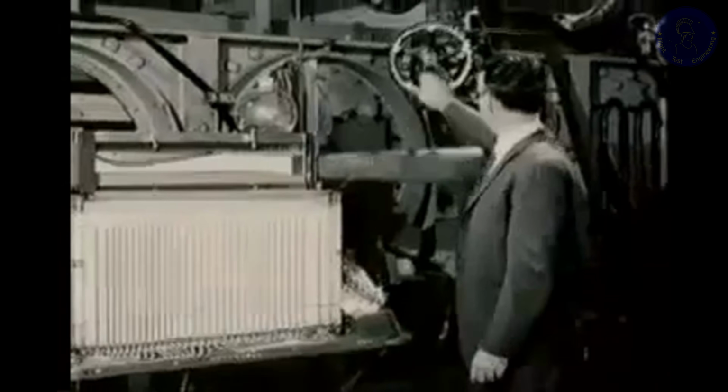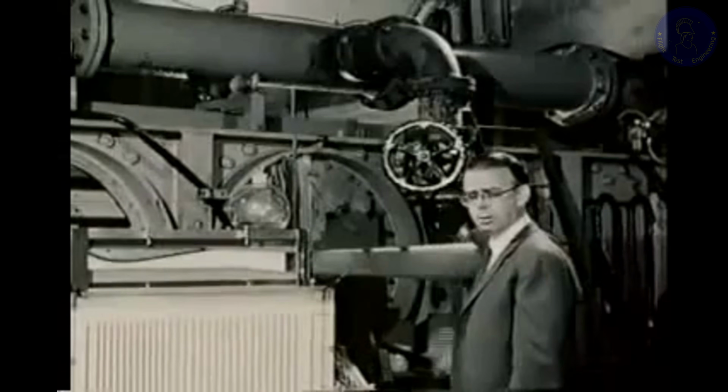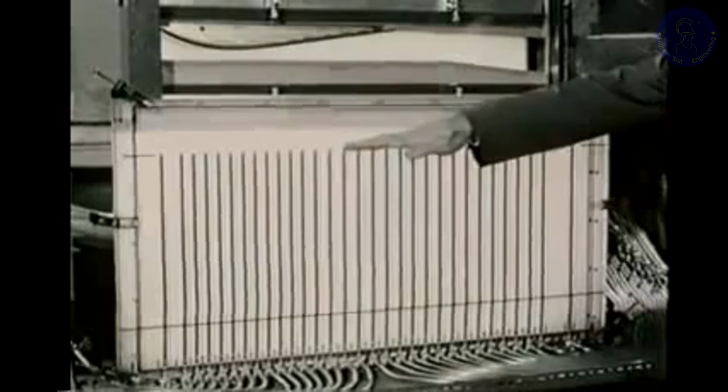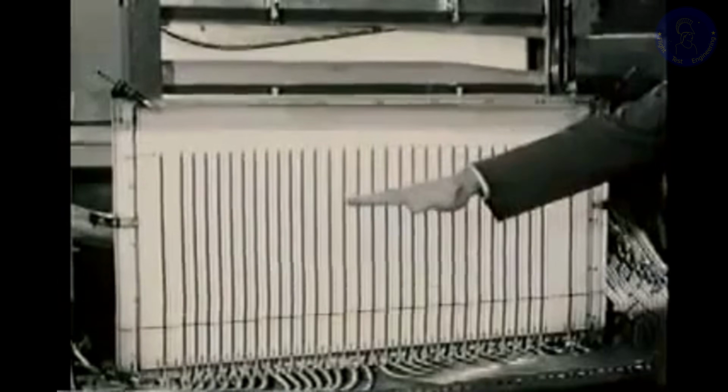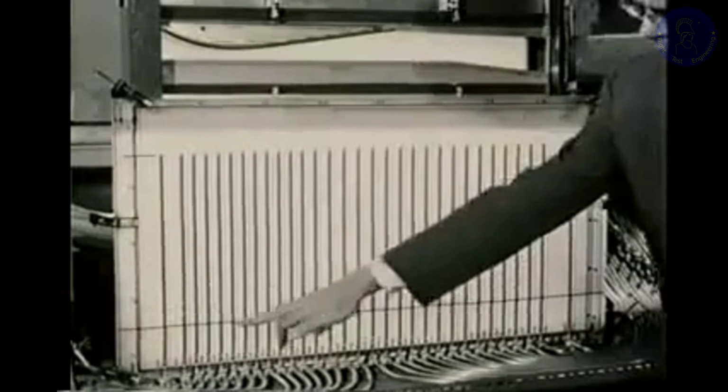Room air at atmospheric pressure enters the channel here, flows from left to right through the channel, through this control valve, and into a vacuum pump downstream. Each column on this manometer board shows the static pressure at the corresponding point on the lower wall, the flat wall of the channel. We've arranged for the mercury level to go down when the pressure in the channel goes below atmospheric. Zero pressure is here.